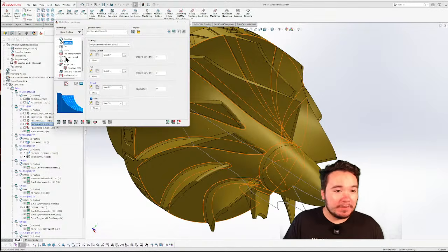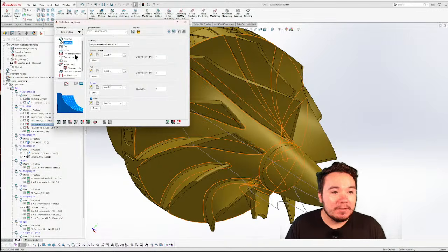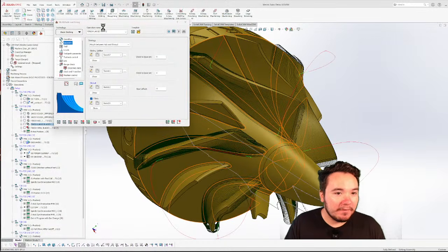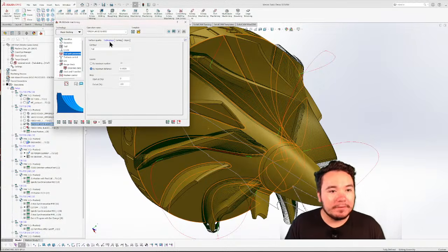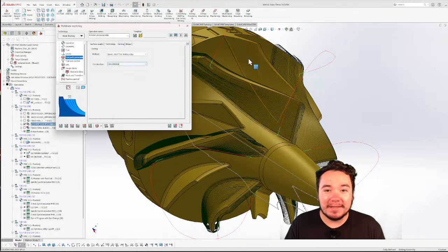But everything else is pretty much the same. The toolpath parameters are slightly different. And we'll see that. And that should just be our step down or step over. There we go. Technology, yep, by number of maximum distance. So 2 thou, 5/10. And we're doing spiral, and we're conventional cutting, just so we don't grab that blade and bend it because it's such a thin blade. I think we're looking at about 12 thousandths thick.